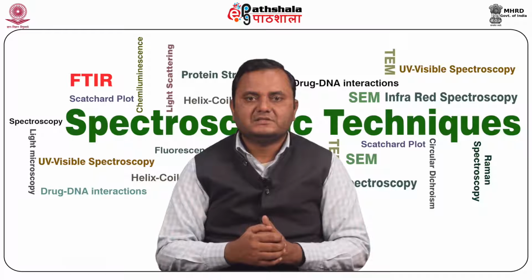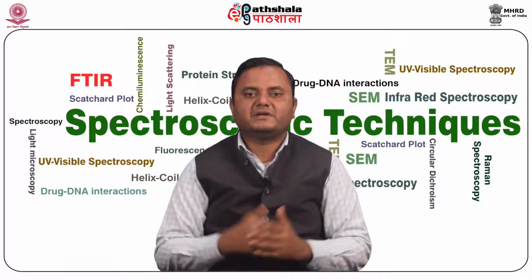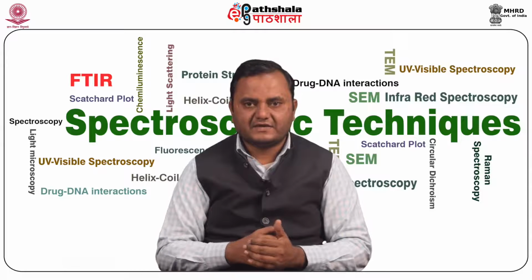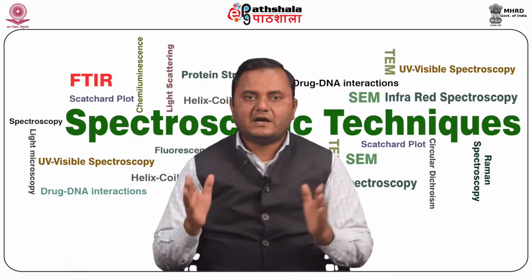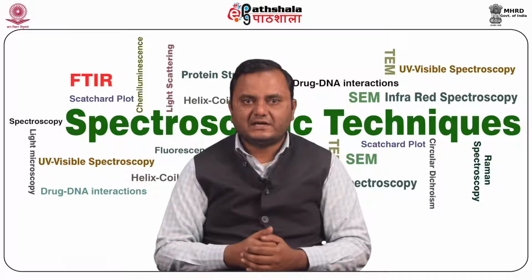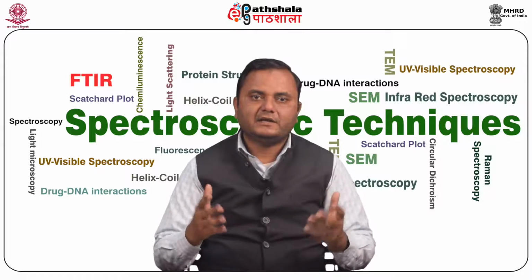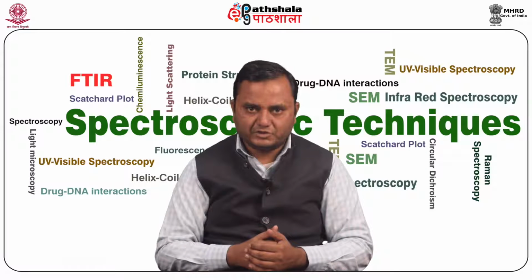Non-dispersive instruments use a filter for wavelength selection for an IR-absorbing gas in the detection system for the analysis of gas at a specific wavelength. Modern dispersive IR spectrometers are invariably double-beam instruments but may allow single-beam operation via a front panel switch.